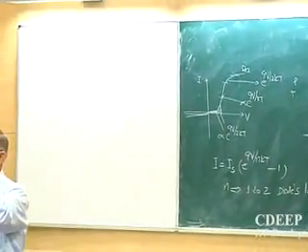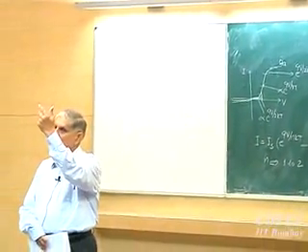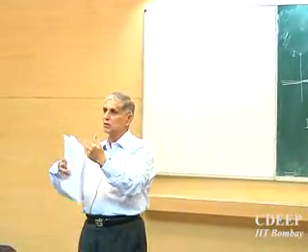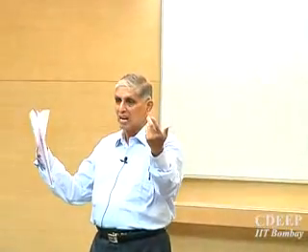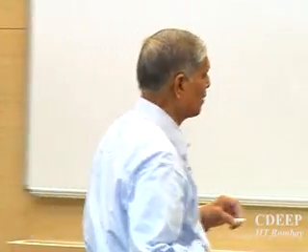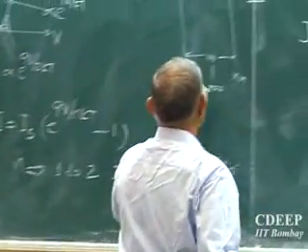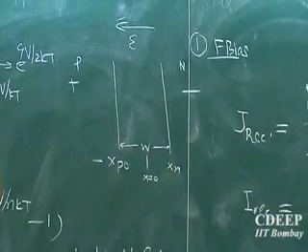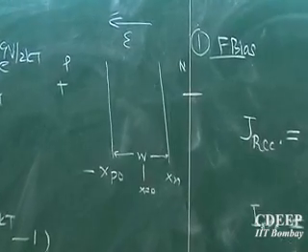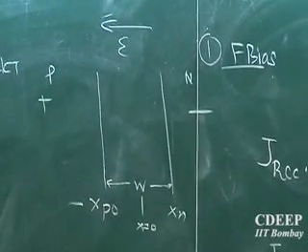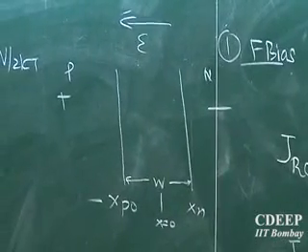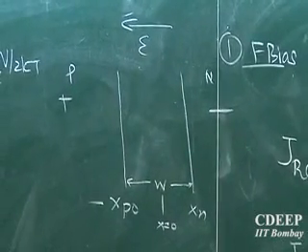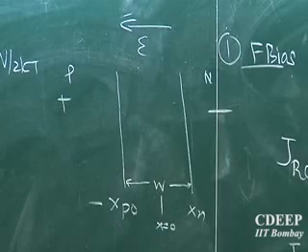Both voltages are in the same sense. The built-in voltage and the reverse voltage are in the same sense, so built-in voltage plus this means the field is larger in reverse bias. Please take it from me, if your E is much larger, electrons and holes will experience larger kinetic energy or larger force. Is that clear? So before they could recombine, probably they will be swept off.